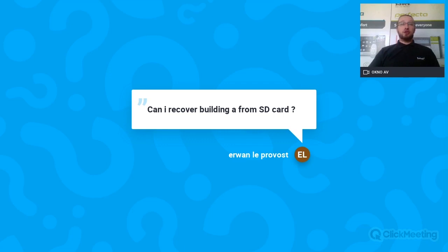Can I recover a building from the SD card? No. Irwin, sorry, but no, you can't, because TSI Builder creates from all the big size files and configuration something that TSI will understand. So I advise you to always go to Documents, then TSI, and always export or make a backup of the TSI Builder projects, which will give you a backup of the configuration.